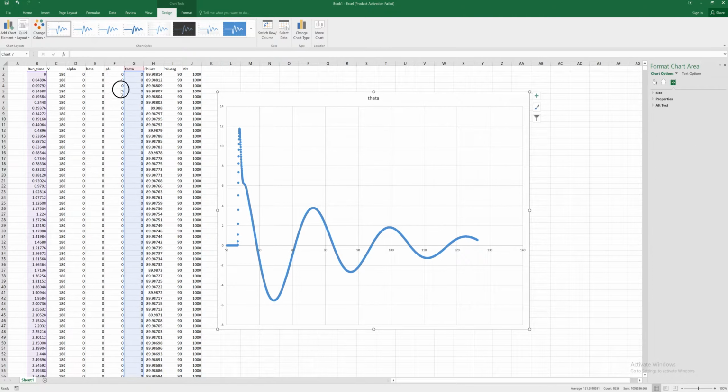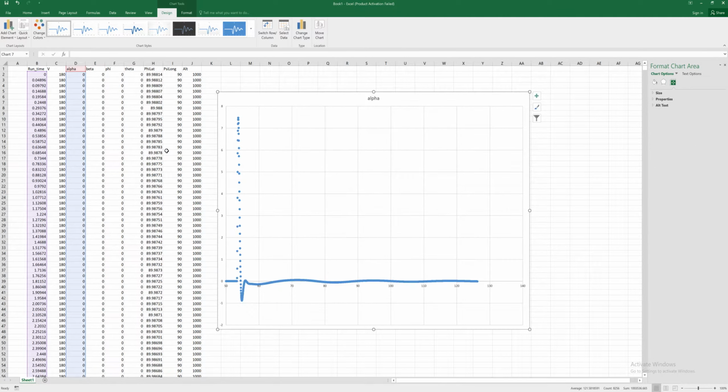Now let's go back to alpha for just a second here. In alpha, you can also see a real slight phugoid mode in there. And again, that's expected. You do have very small changes in angle of attack, but compared to the short period, these changes in angle of attack are really, really small. So again, the phugoid is mostly a change in velocity. The angle of attack actually doesn't change much during the phugoid. Okay, so these are our longitudinal modes.